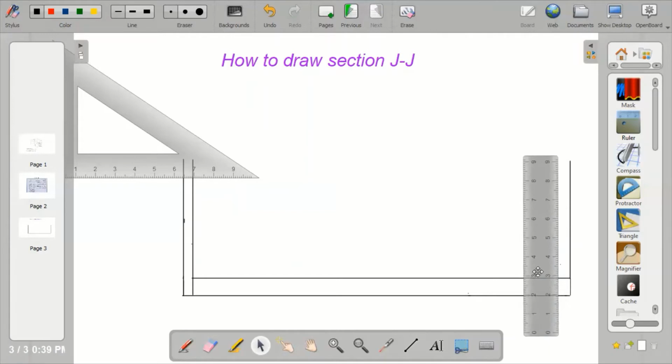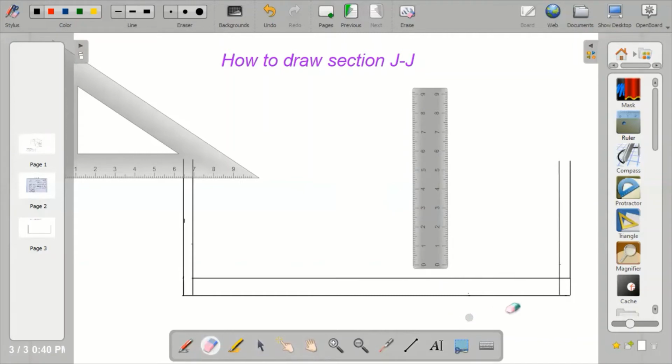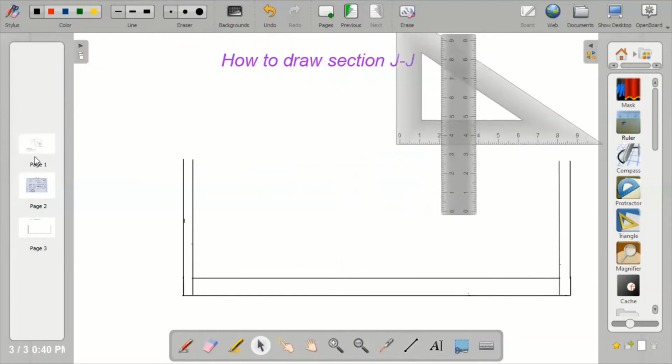Now when I'm drawing my wall, it will go all the way through, because the wall will start from the substructure to the superstructure. Substructure means the part that is underneath the building. These are the foundation, the hardcore, the concrete oversite, the blinding. These are the parts that are underneath the wall. But superstructure is above the foundation. So I've been able to draw my external walls.